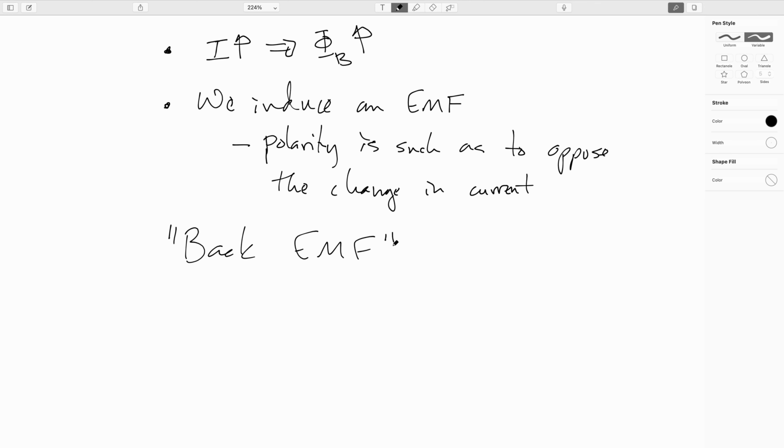On the other hand, as the RPMs go up, the back EMF increases. This is opposing the EMF being supplied by the battery, which means you're decreasing the current through the motor, but that means it actually becomes a less effective motor in the sense that it can provide less torque.